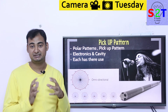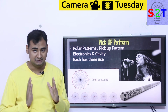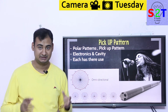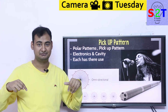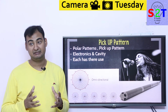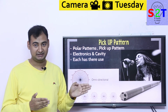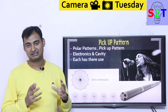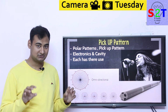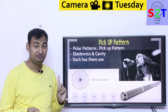If you have two cavities done correctly, that gives you a noise cancellation microphone. And the aspect of noise cancellation is you don't have to use electronics for it. It's not a Bose noise canceller where it's receiving the sound and processing it. It's generally used for, let's say, avionics. It's crucial for basically an air traffic controller who needs to hear the pilot. They cannot be like, oh, the sound is not working, the battery is discharged. No. So what they do is they simply have two capsules, basically two microphones pointing away from each other, and that gives them figure 8.